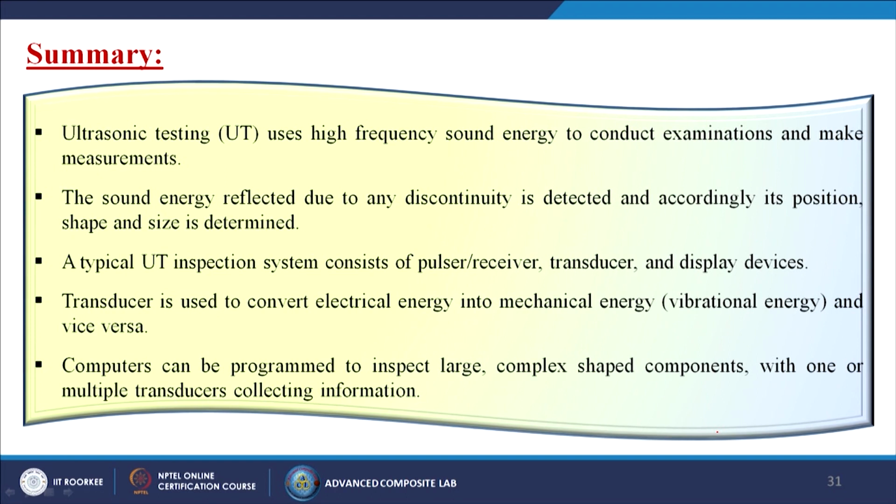A typical ultrasonic testing inspection system consists of pulser/receiver, transducers and the display device, a CRT screen. Transducers are used to convert electrical energy into mechanical, vibrational energy and vice versa. Computers can be programmed to inspect large complex shaped components with one or multiple transducers collecting information.